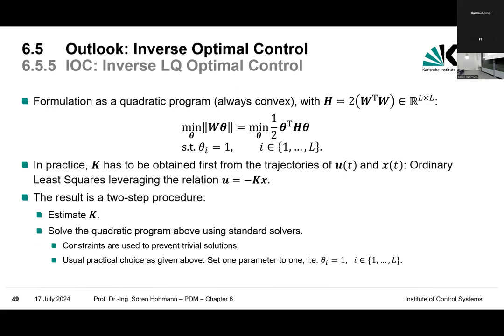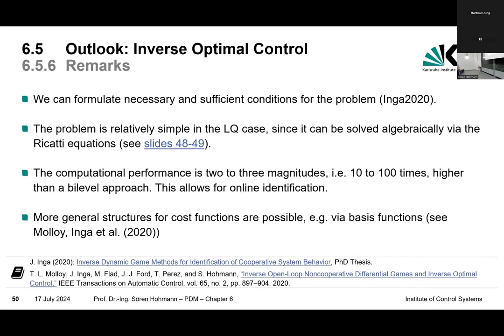That's the basic idea. So you can use the information that every solution which has a quadratic performance index has to fulfill the matrix Riccati equation. And if it's not fulfilled, I have the wrong parameters, right? And therefore, we can adjust the parameters according to that. That's the basic idea. And this applies to linear systems, nonlinear systems, etc. And works quite well.